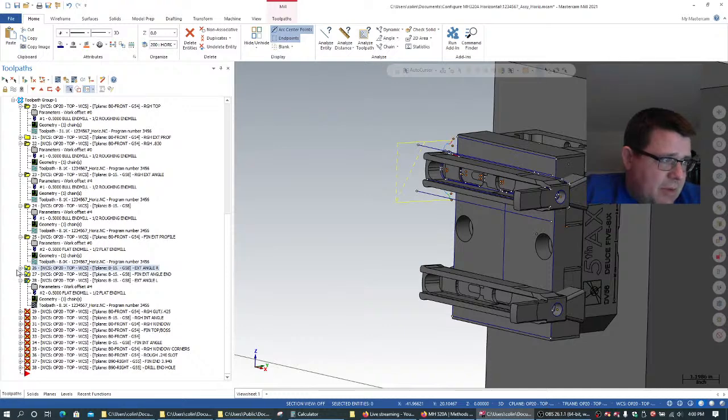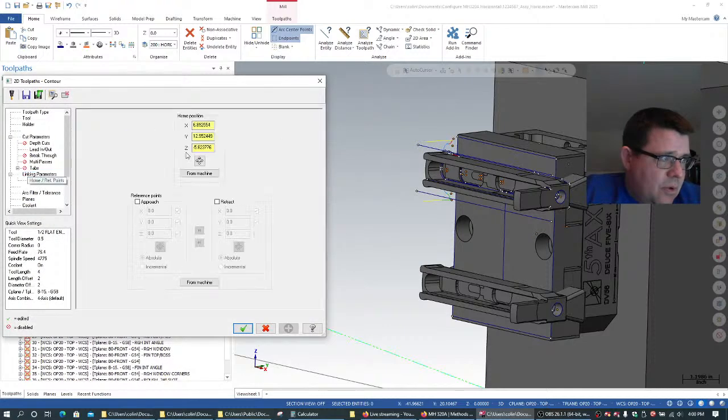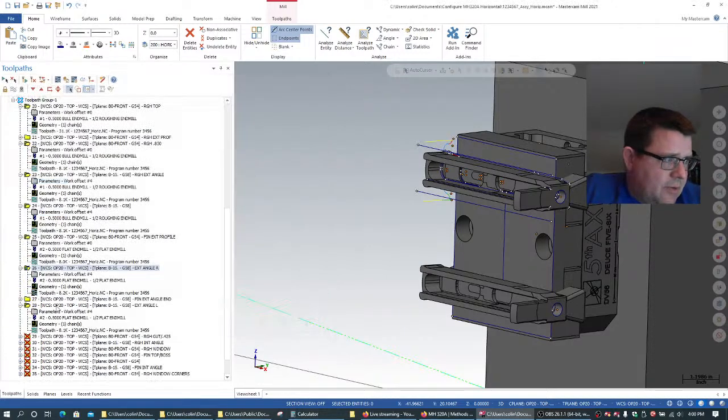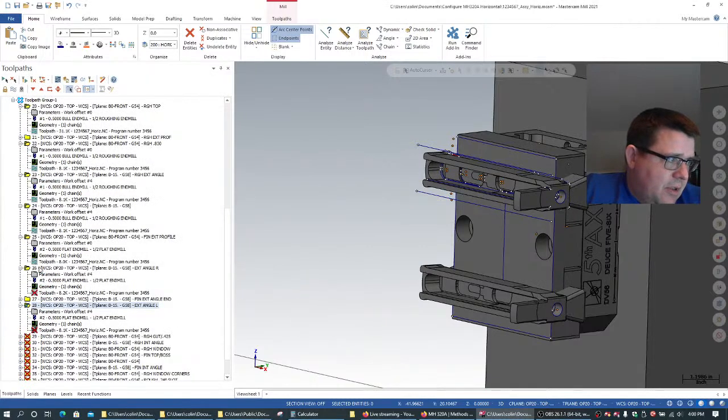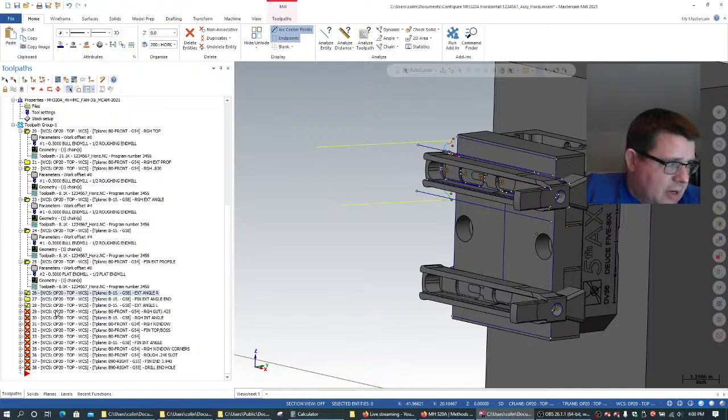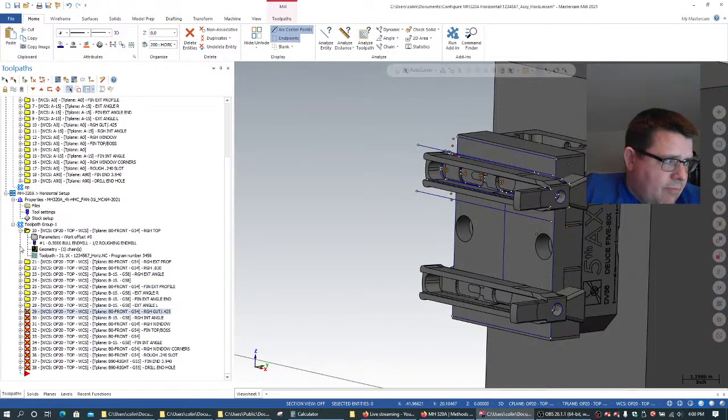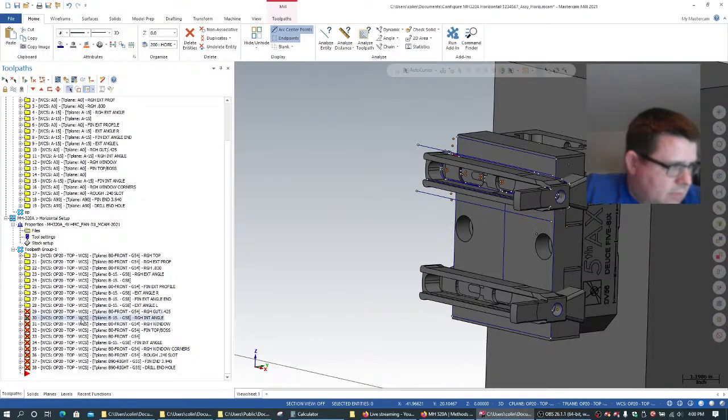And let's see, that goes back to B0. So here we're going to do a 3-inch incremental approach, and finally a 3-inch retract on the last one here. All right, so minus 15. Let's see here.